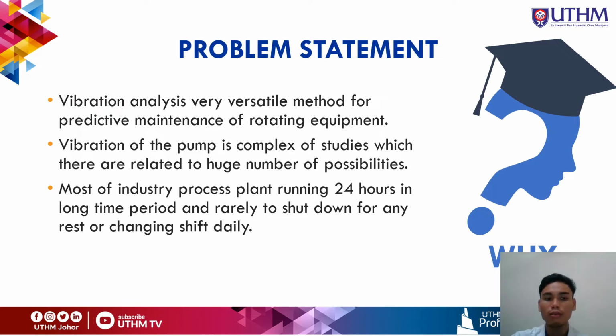The third is that most industrial process plants run 24 hours over a long time period and rarely shut down, not even for a rest or a daily shift change. So when the pump is running without stopping, we must do the maintenance without stopping the pump. This vibration analysis can decrease the downtime for shutdown maintenance.